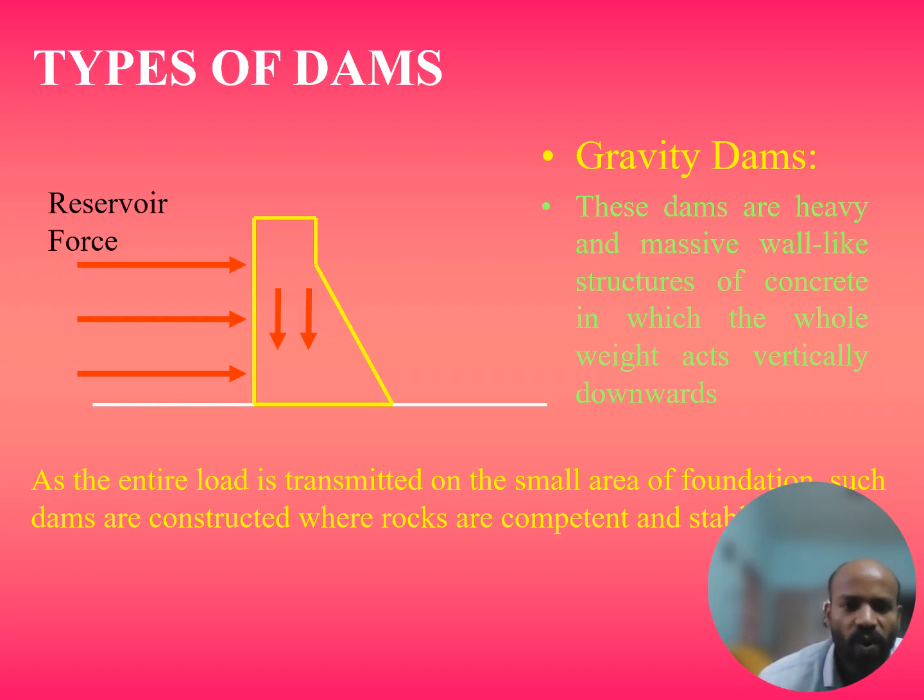Here the entire load is transmitted over a small area of the foundation. Therefore, the soil pressure will be maximum. Therefore, the underlying soil should be of maximum safe-bearing capacity. Therefore, a gravity dam is normally preferred over a soil medium of rocky stratum. If the underlying soil is of rocky stratum, only then a gravity dam is preferred.